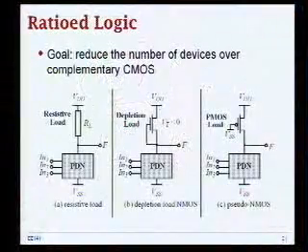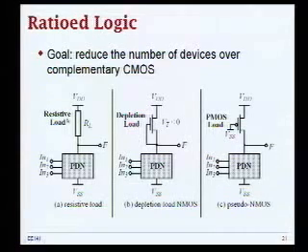Thank you. So basically what this does is, let's say I have some resistive load to my pull-down network. I still implement the same pull-down function and pull this down to logic 0. I'm not going to say 0, but logic 0. Okay, you'll see that in a moment. And when my pull-down network is not pulling down, what I have is basically pulling up through this resistive load.